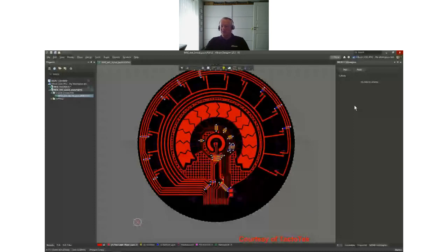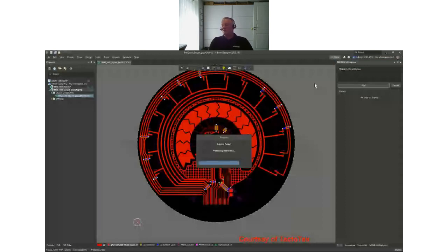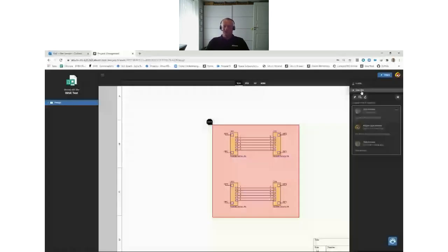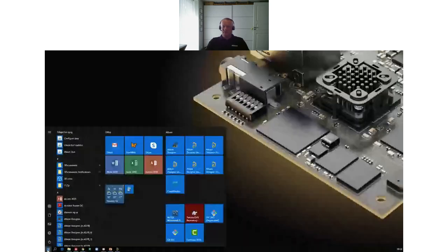So I'll just enable the panel here, and the only thing I actually have to do is push the design. So let's give him a comment, say please check with the enclosure, and just post it. Now Altium will then generate native data for the MCAD, and all he has to do is, let's sign out of this one here, activate SolidWorks.